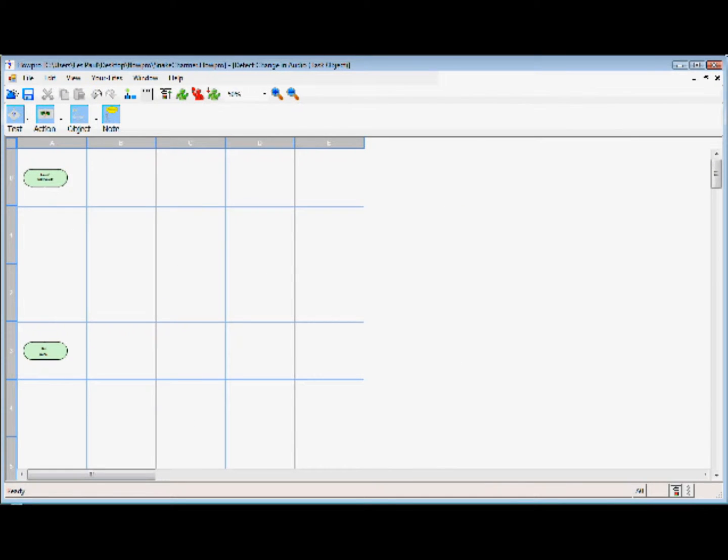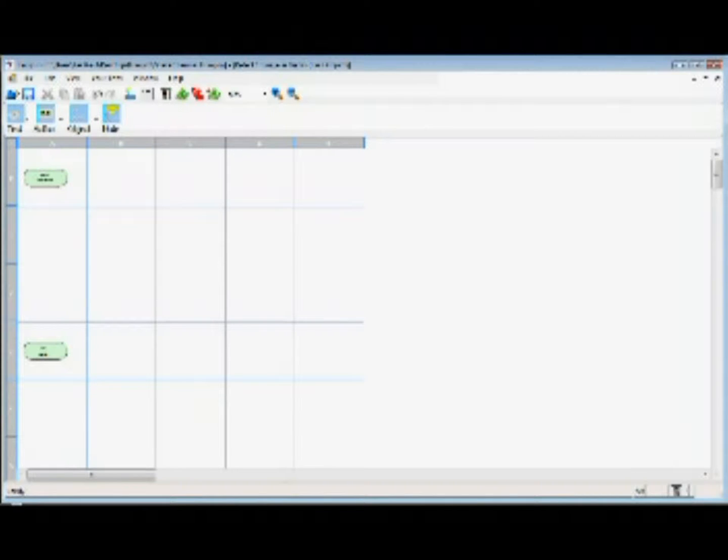Within this new object, I'll need to create a way for the frequency of the audio to be compared to the previous state. The value of audio frequency is stored in register 16 as a binary number. If I copy the value of register 16 into another register, it will give me a way to compare the two states of the audio. With a change of audio, the value in register 16 will change, but the other register will still have the previous value. Comparing the two registers will tell us if there is a change in the audio.